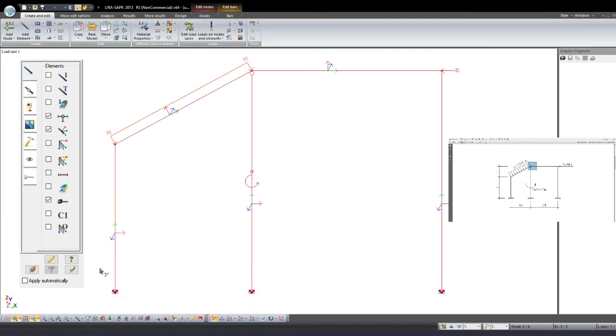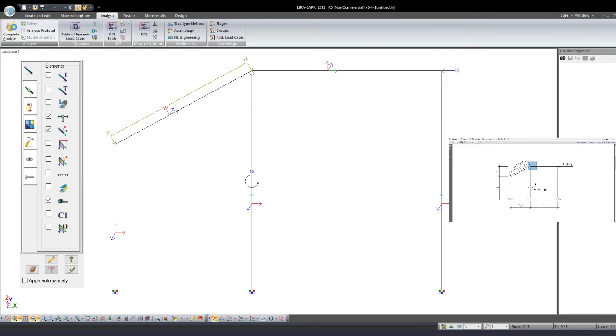stiffness. I select all elements, touch material properties, touch add, rect bar. For this, I write 3E7. After this, 20, 20, touch OK, touch apply, and after this, oh, I forgot one serial part. I forgot to pack the model. Do pack model. Okay, after this I go to analyze, touch complete analyze, analyze all this, go to result.